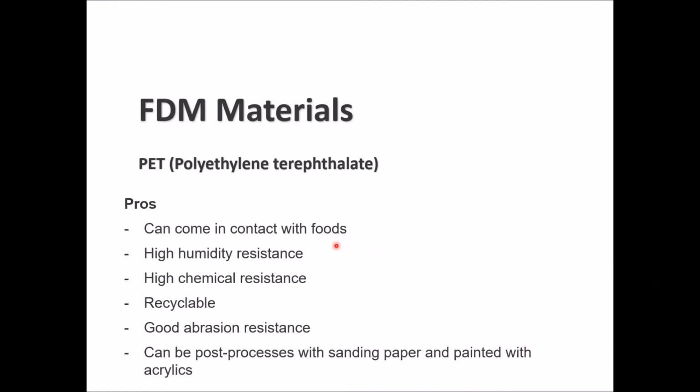Good sides for this material: it can contact foods without any kind of harming or side effects. It has a high humidity resistance, a high chemical resistance, it can be recycled, it has a good abrasion resistance, and it can be post-processed with sanding papers and can be painted with acrylics as well.